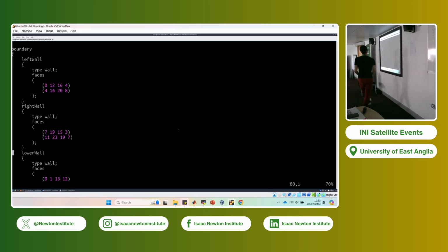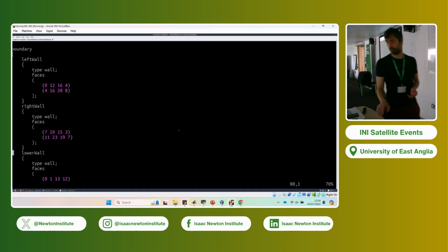So potentially, I could put all these faces under the same boundary name so that I only have to define their boundary conditions once. Here, the tutorial is taken from the OpenFOAM guide, so it splits it into 3 different boundary names, which means that when we define the boundary conditions, we need to define a boundary condition for each of these names. Or OpenFOAM will complain saying that it doesn't know about the boundary conditions.